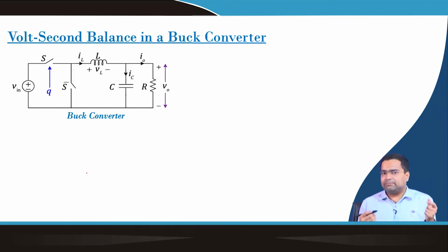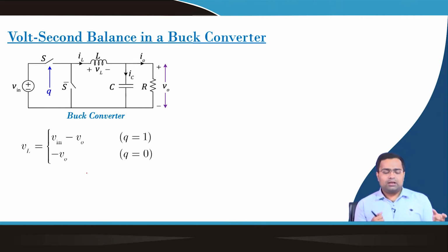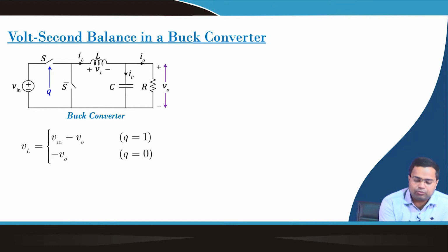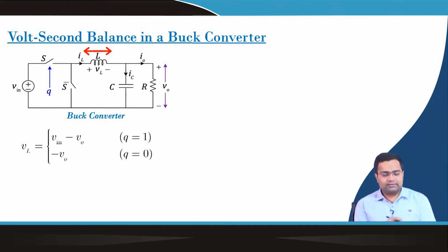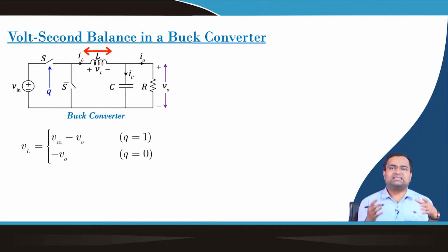Okay. Now, this is the well known volt second balance in a buck converter, any DC-DC converter. What is the volt second balance, that we know, but just to revisit the concept, let us consider the voltage across the inductor, that means we are talking about this particular voltage. This voltage changes its polarity when the switch status changes.